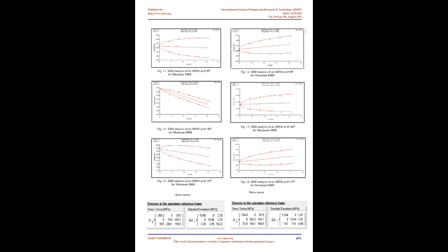Residual stress result for specimen 01, 19, 13, 17 and 14, min RA, max RA, and min MRR, max MRR. 4. Conclusion. After conducting the cylindrical grinding experiment on OHNS rounds workpiece, the following conclusions are made. Work speed, RPM, and number of passes are the main affecting parameters for surface finish, whereas feed, m/min, plays an important role in deciding the metal removal rate, MRR.